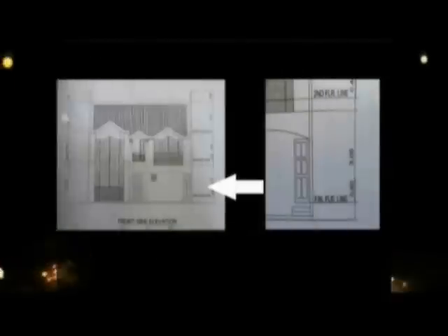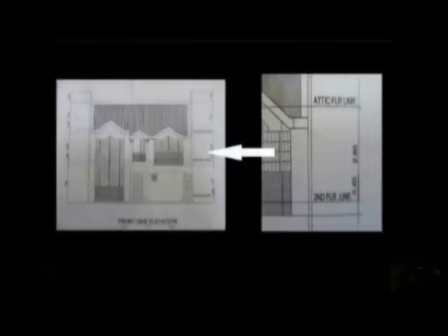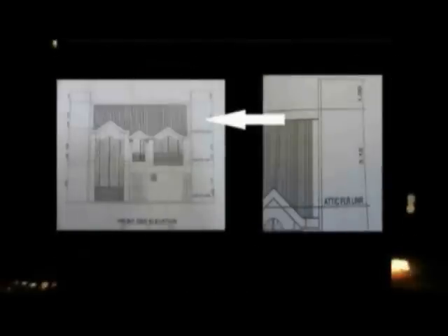This is the front view of the house. The measurement from the NGL to the first floor ceiling line is 3.6 meters. And from the second floor line to the second floor ceiling line is 3.2 meters. And lastly, the height of the second floor ceiling line to the attic ceiling line is 3.12 meters. At the right and left side of the house, we can see that there is a firewall built that extends 1 meter from the ceiling of the attic.